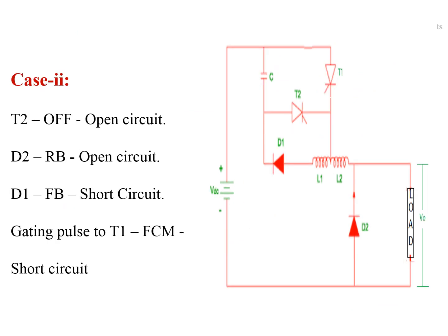In the first case, the capacitor charges with the upper plate as positive and the lower plate as negative. This lower plate is connected to the anode of thyristor T2, so thyristor T2 comes into the off state and acts as an open circuit.